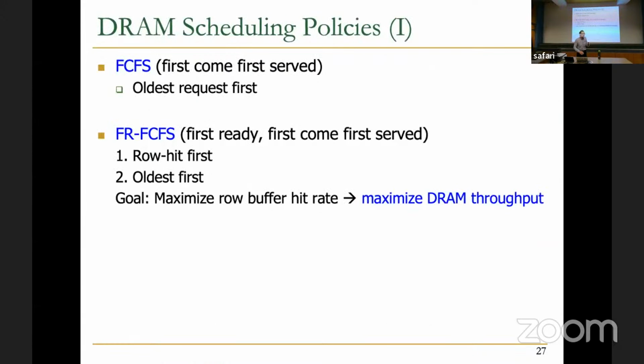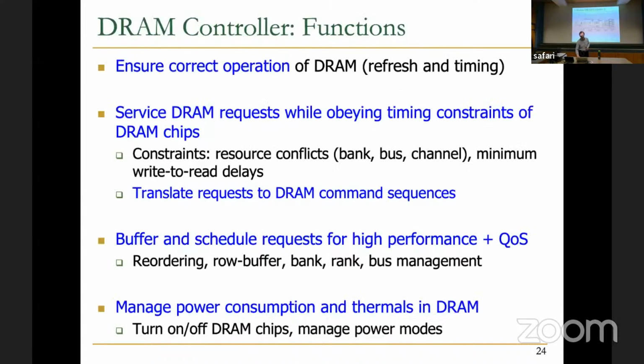But you cannot just provide correctness today. You really need to provide performance also, because if you just need to provide correctness, you can actually design a very poor memory controller, right? Because it can basically, for example, say first come, first serve. That's oldest request first. And it can also say, I'm going to obey all timing requests, but you can basically add even more timing slack than timing parameters. So the problem basically is not interesting because your competitor is going to design a much better memory controller, if you actually say, I'm going to design a poor memory controller. That's never the goal. So basically my point is, you cannot decouple the performance and correctness issues as much. You have to design all of these.